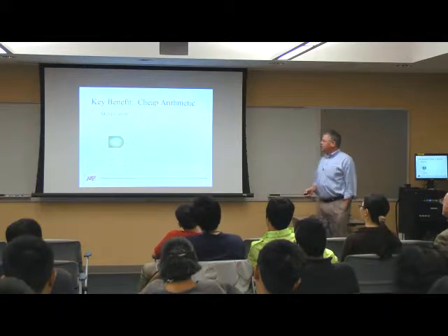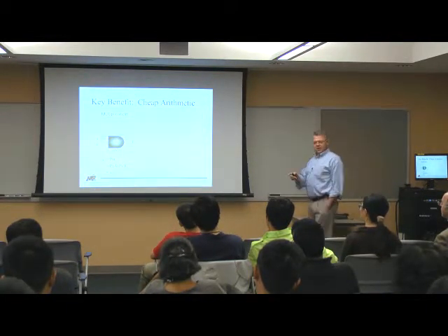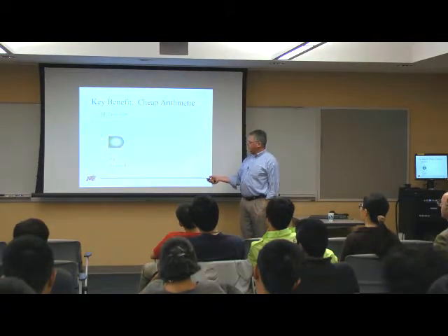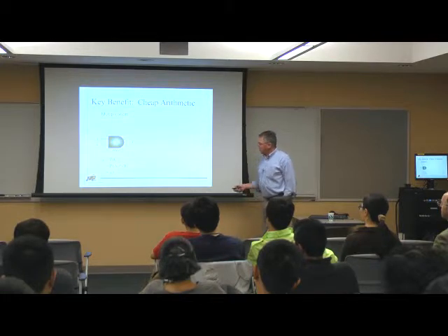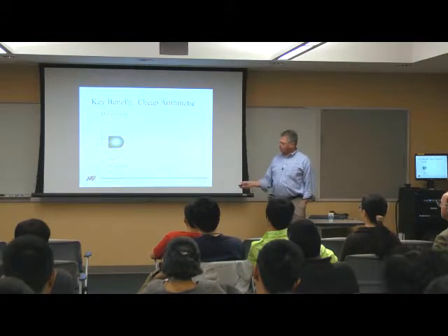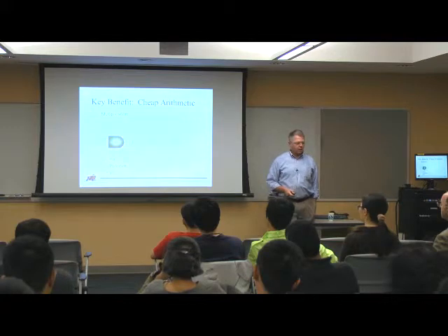Another benefit is that arithmetic is really, really cheap. If I think about these streams of bits, I have a stream of bits coming in A, a stream of bits coming in B, and I'm performing the AND of those. Mathematically, I'm saying the probability of C being a 1 is the probability of A being a 1 and the probability of B being a 1.